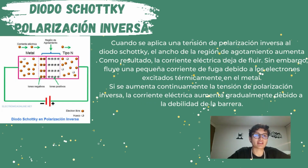Reverse bias Schottky diode. If the negative terminal of the battery is connected to the metal and the positive terminal of the battery is connected to the N-type semiconductor, the Schottky diode is said to be reverse biased. When a reverse bias voltage is applied to the Schottky diode, the width of the depletion layer increases.